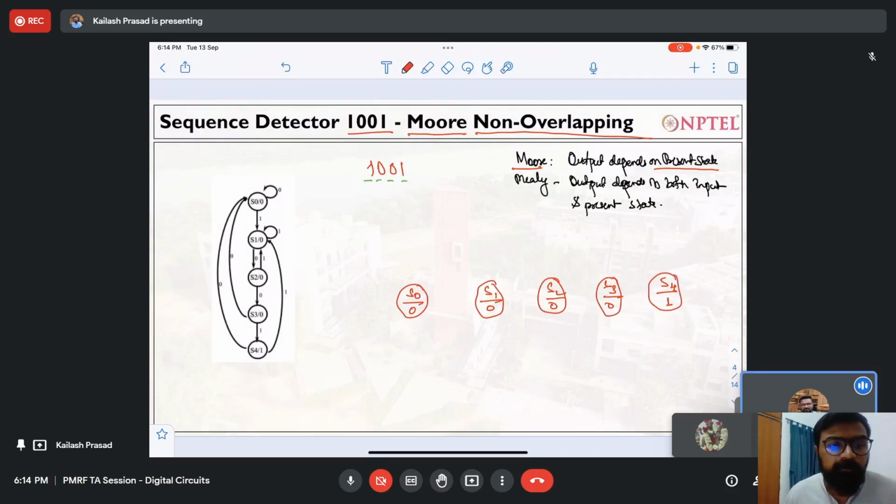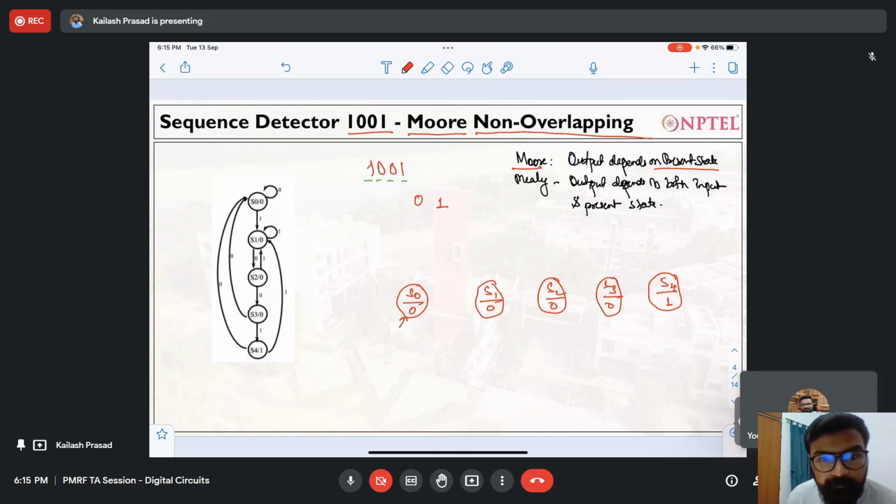Now what I have to do is design the 1 0 0 1 detector. Suppose I am in the initial state. We will check for two conditions, right? Either the input is 0 or the input is 1. If my input is 0, can anybody tell me which state I will go to? I will start here. And if my next input is 0, where will I go? S1? Anybody else? It stays in 0. Yeah, it stays in 0.